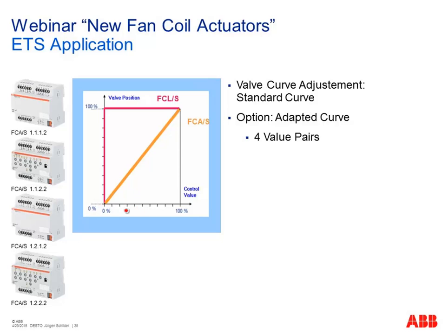Means if I have any control value, maybe 50%, the valve will be opened 50% as well. And you see here from our blower actuator, I mentioned already that it's possible to control also valves, but here in a very simple way only. Any control value greater than 0 leads to complete opening of the valve behind, because there's only a relay behind and no modulation, no positioning possible.